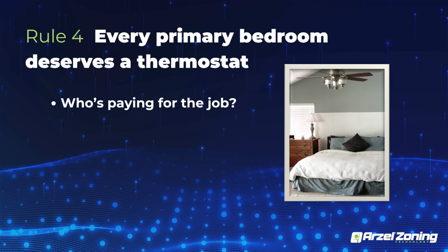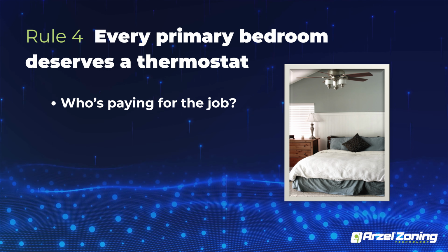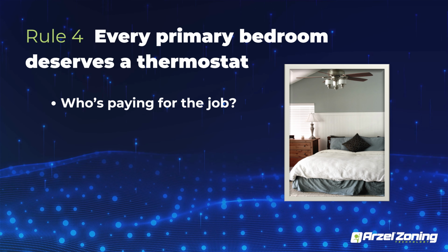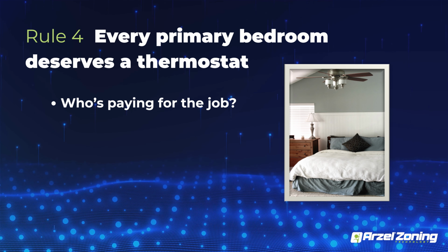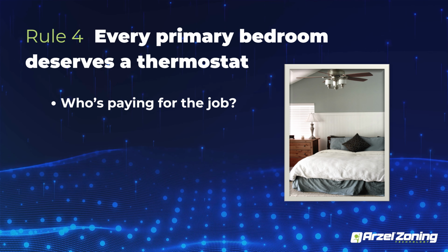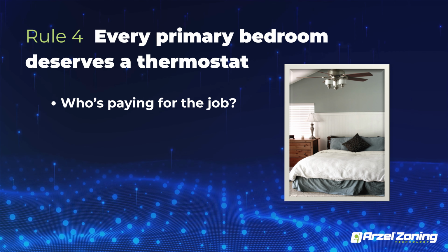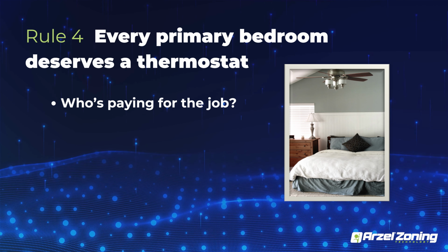If that customer, every night when they go to bed, say they go to bed at 10 o'clock, and at 9 o'clock that thermostat comes out of setback and cools their bedroom off to 72 degrees, and when they come upstairs at 10 o'clock that room is spot on, 72 degrees every night when they want to go to bed, how happy are they going to be? If the thermostat's residing in the hallway, and now the bedroom's more comfortable but it's not really at set point, how happy are they going to be with their big investment that they made in zoning?